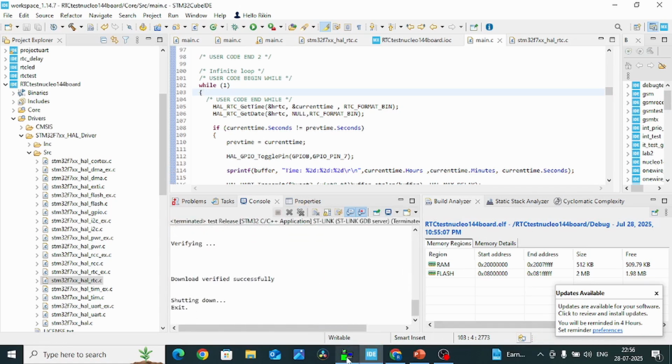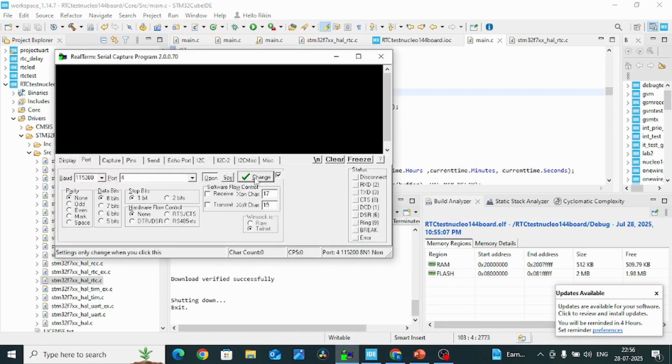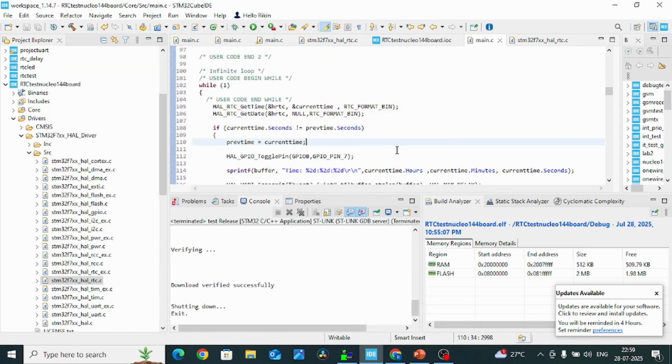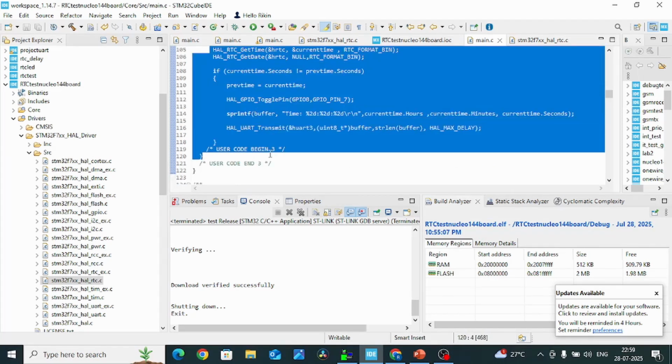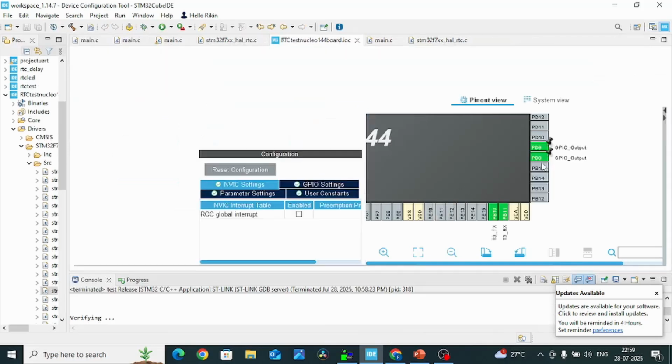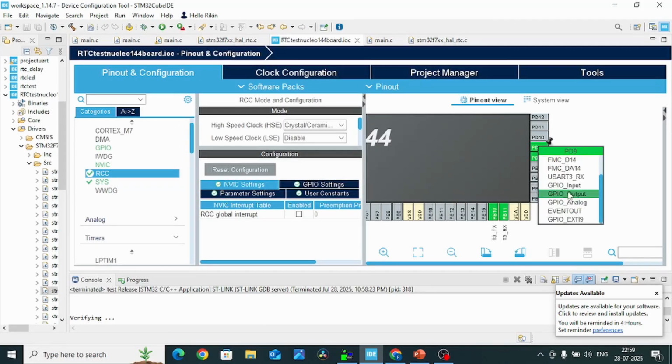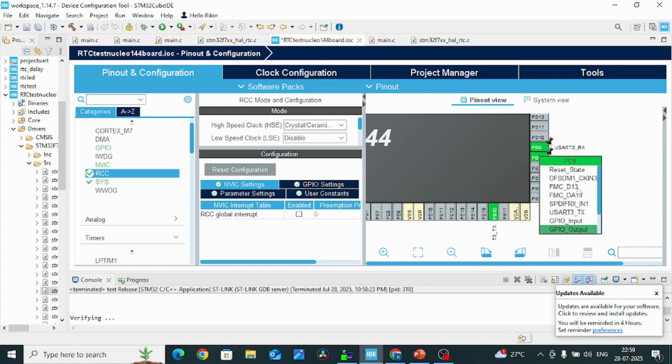Now it is completed. And I'm extremely sorry for one correction. So let us first of all copy this code. And one mistake which I made: instead of this GPIO, we have to use UART, right? That's why my code was not working properly. But now as I use this, my code will regenerate. So I have to rewrite this thing. So I'm just copying those. And now it should be UART, right? Not GPIO.